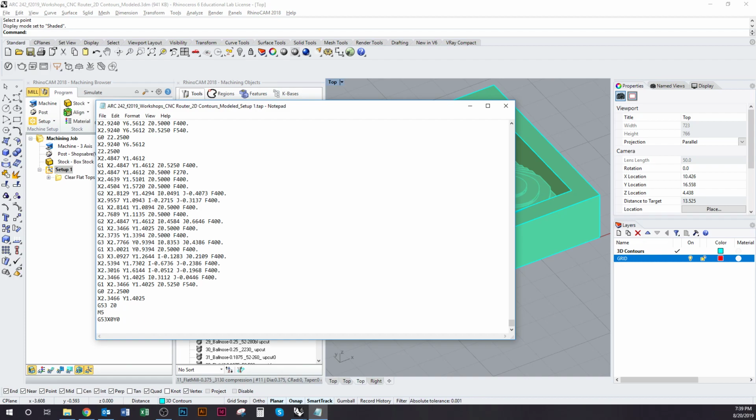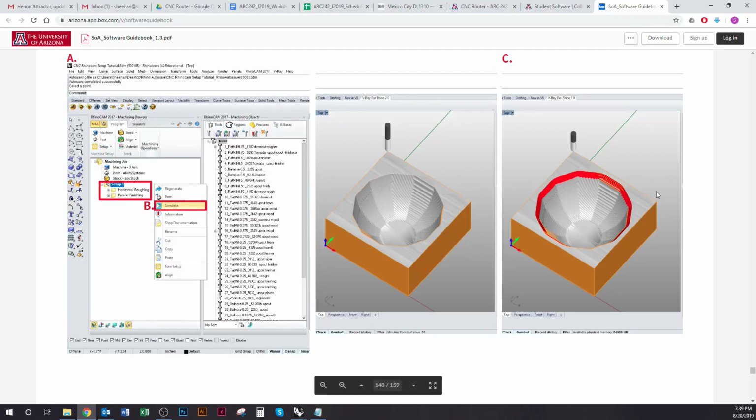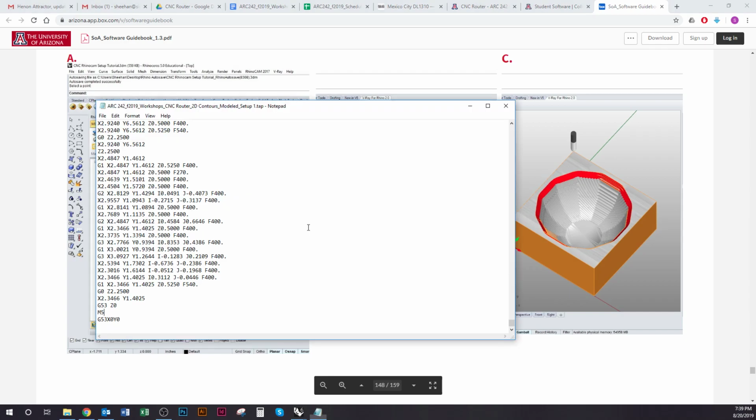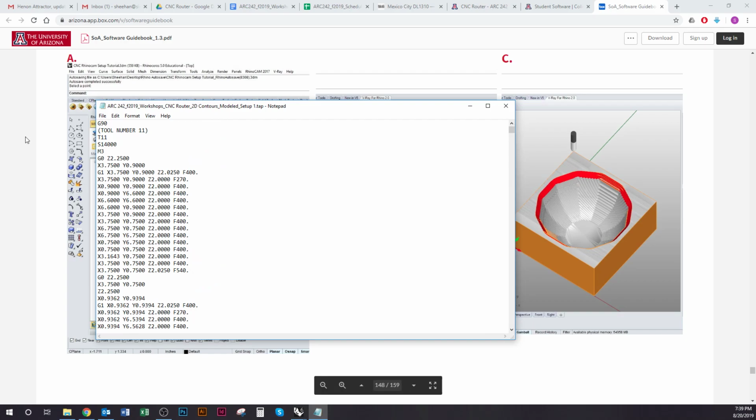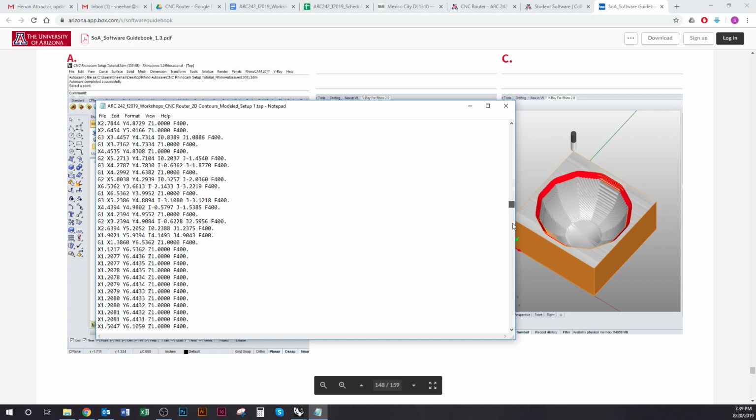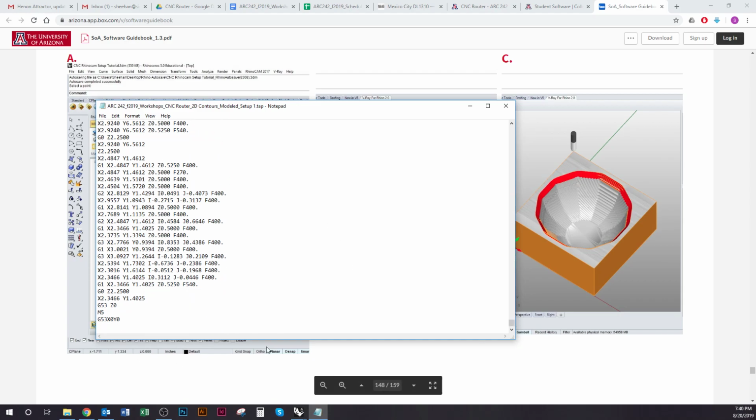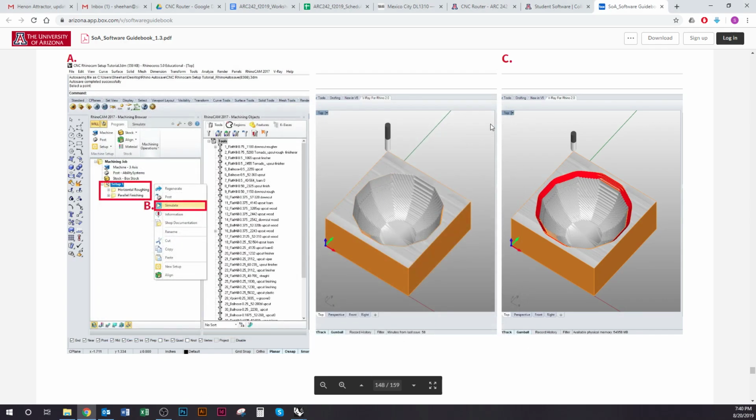When you have a file that's set up like the PDF tutorial with 2 different toolpaths and 2 different router bits, you'll find that M5 will appear, and right after the M5 it'll give you a new tool number. That's how you know when you have to change the bit and what to change the bit to. So that's just to check that our file is set up in the right way, that we have all the tool changes we want.